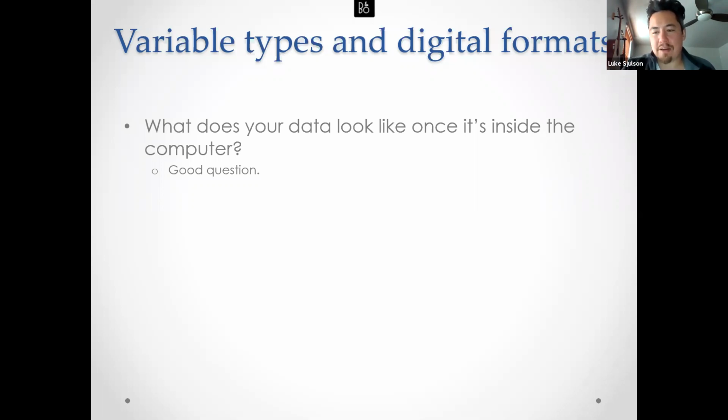So if we know that knowledge in advance, then we can say, well, we don't need to sample at higher than that. So we can put a low pass filter at, say, 8 kilohertz. But we're picking that 8 kilohertz or 10 kilohertz or whatever cutoff based on our prior knowledge of what we expect action potentials to have, what frequencies we expect them to have. And then we sample based on that.